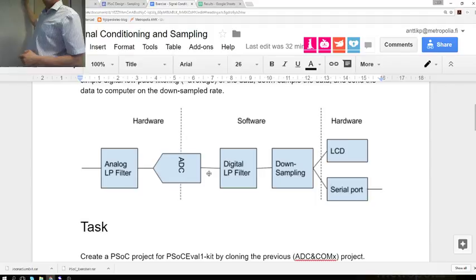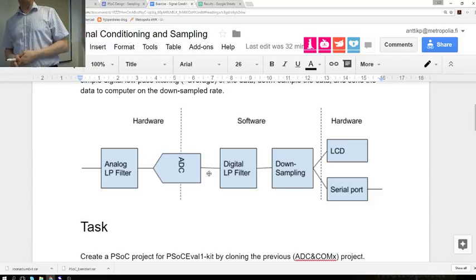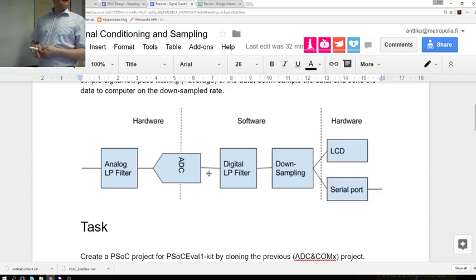Okay, so basically we start switching these on, off, on a 90-degree phase. We get control of how fast the charge goes from one end to the other, which fundamentally at high frequencies starts to look like a resistor.